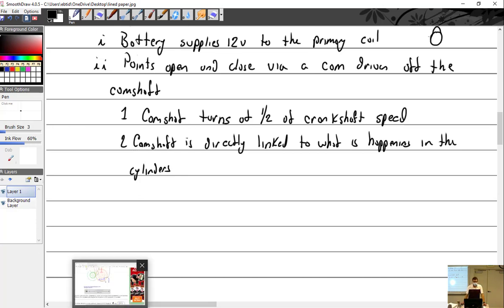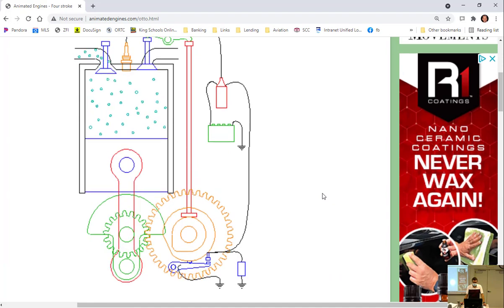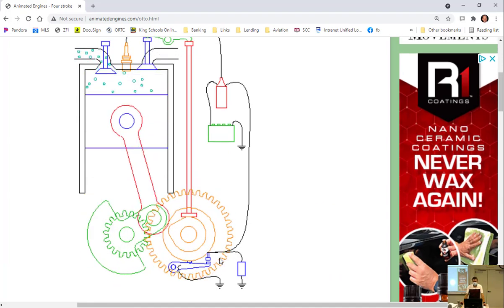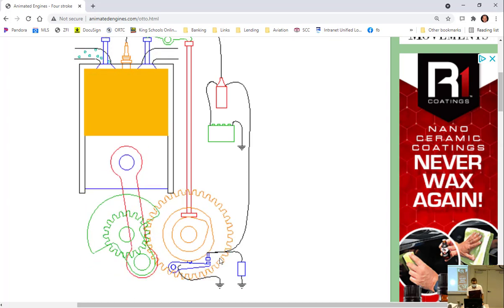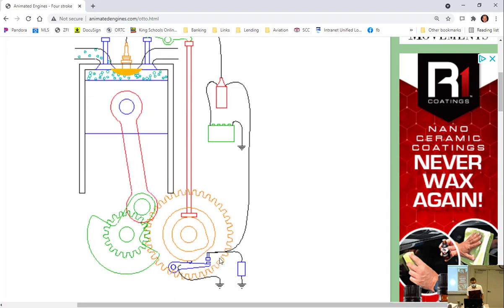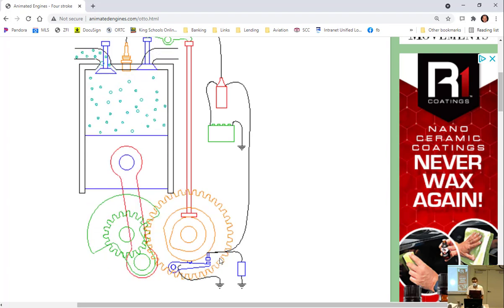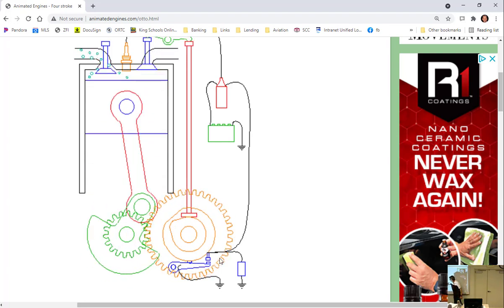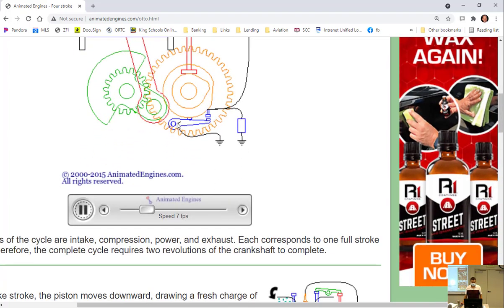Because if you really think about it, one of the things we have to do as a mechanic is tell this ignition system when to fire. What if I took this little breaker point right here, and this little nub right there, that's called the follower, that rubs against that. If I took this whole little blue thing and rotated it around so it was over here, rotate it up a little bit. There we go. I rotate this thing in the direction that the camshaft is going. So instead of being here, it's vertical over here. Nothing else changes. I just take it and start rolling it.